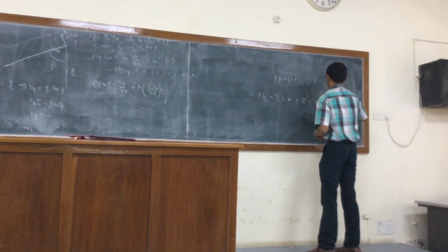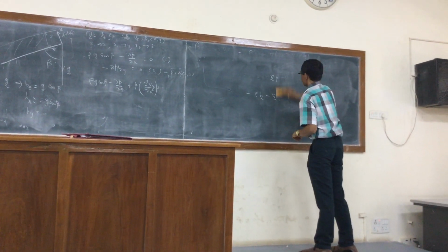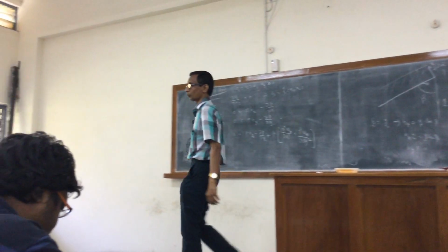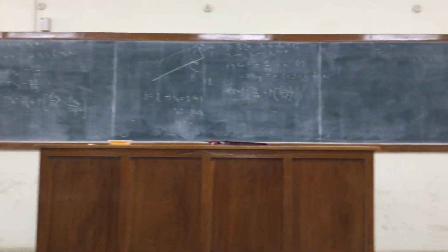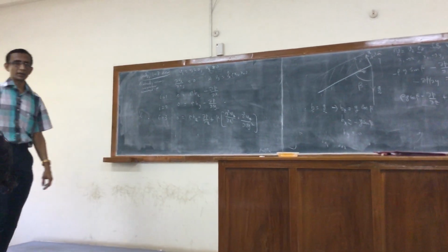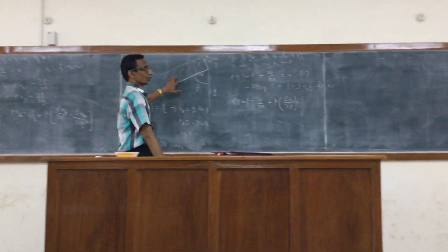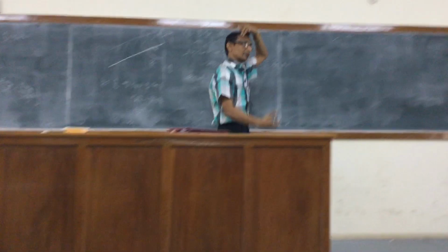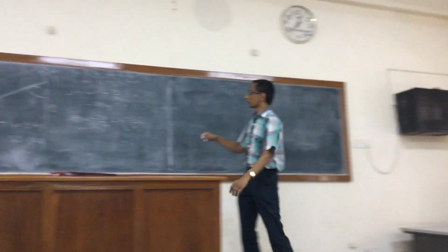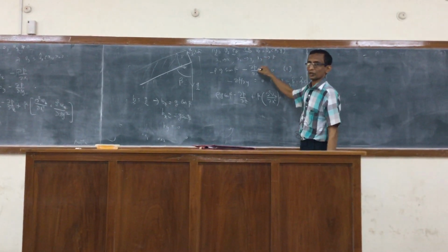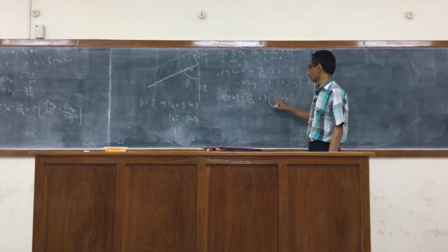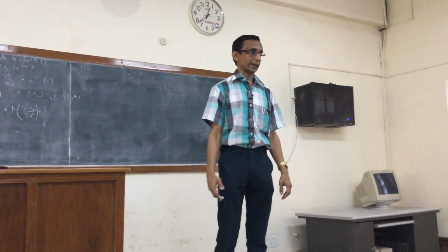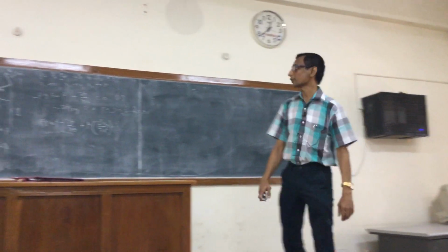An important thing to remember, which we haven't discussed at all, is the question of boundary conditions. Because we were assuming steady flow, the question of initial condition doesn't arise, but when you have dependence on position, you all know that if you have a second order derivative, then we need two conditions. The pressure has only a first order derivative, so you need only one condition on the pressure, whereas you need two conditions on the velocity component Vz with respect to x. We'll see now what those conditions are.